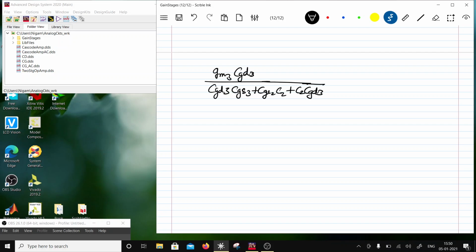So this is my left hand side pole 2. And if I equate this to 1 over, so I'll do a minus sign here, C times of R minus 1 over GM3, that would happen. And in that case, I have to find out R.